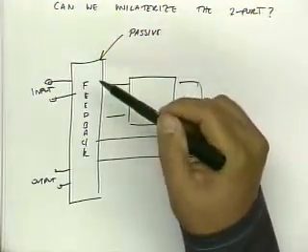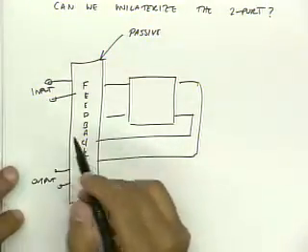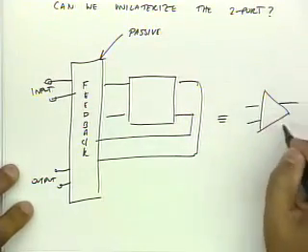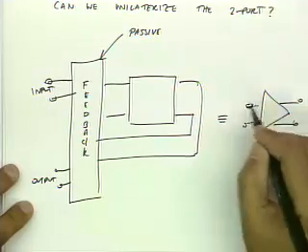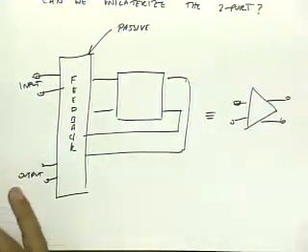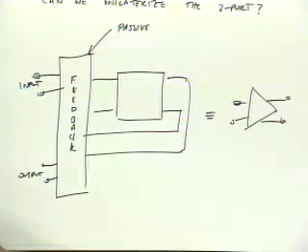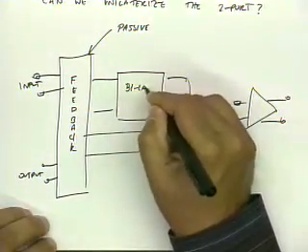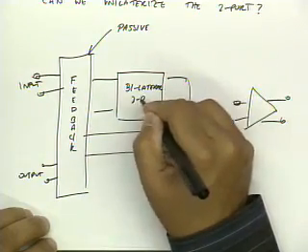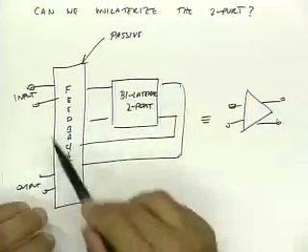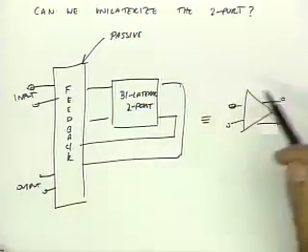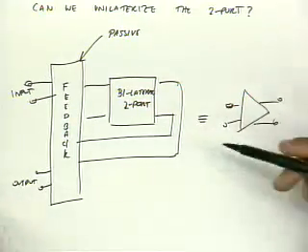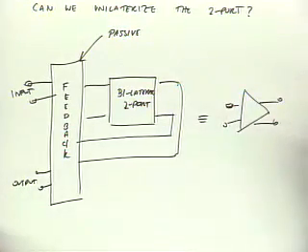And the idea is that I want to create a new two-port, so this is now equivalent to a new two-port, which is unilateral. Okay? I haven't cheated, right? I'm not dissipating any more power than I was before. I still have a two-port. This is my bilateral two-port. And I'm now going to provide some feedback and make it a unilateral two-port. And the question is, if I do this, can I actually get more gain out of my device?